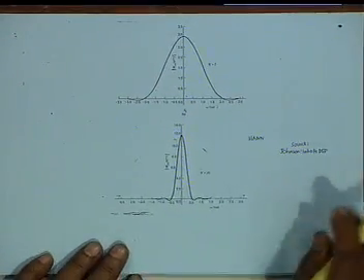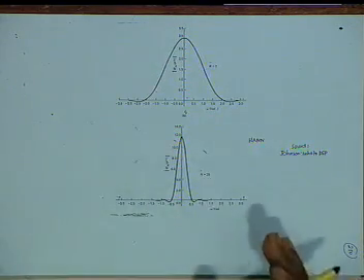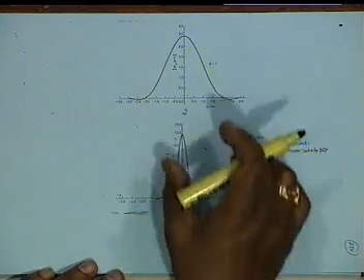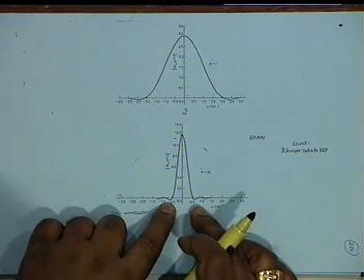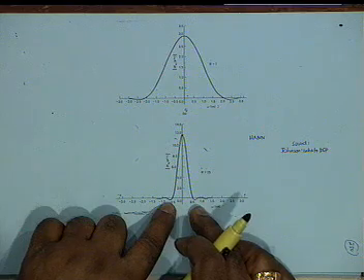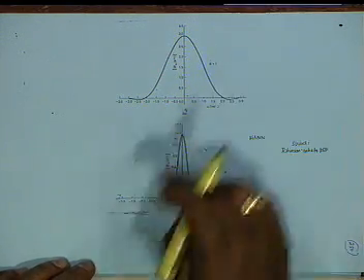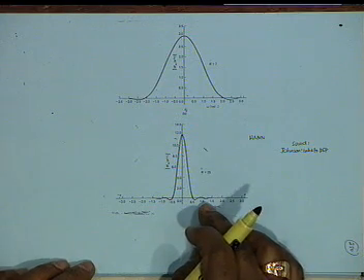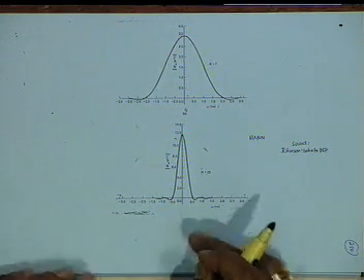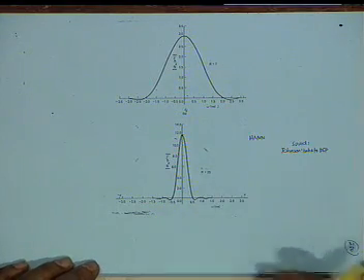Now what is the main lobe width here? About 4 radians. You see how much it has increased? It can be decreased by this. This is 1 radian below that of the rectangular, but the side lobe height increases as compared to capital N equal to 7. It is still smaller than the rectangular window, and that is where it counts. Rectangular window is hardly ever used.